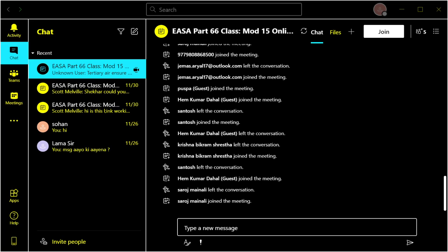Filters, you'll have a low pressure filter and a high pressure filter. A low pressure filter tends to be a wider gauze, that initially grabs the big bits of debris that can potentially be in the tank. And then you have a high pressure filter, which would be finer gauze. Usually they're all a wire gauze, so you can actually clean these. You can put these in an ultrasonic bath. For you guys, you'll just go to stores, get a set of clean ones, take the old one out, and it will go away with the paper as well.